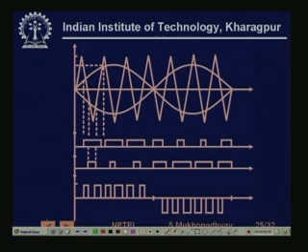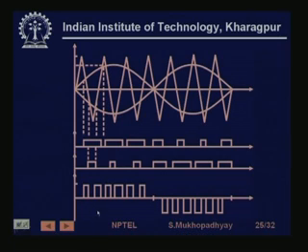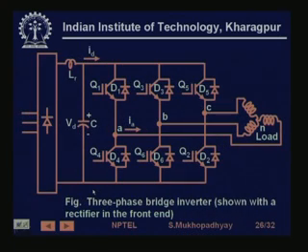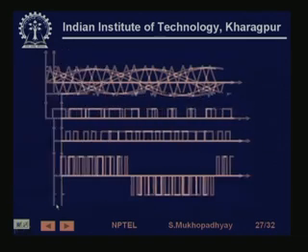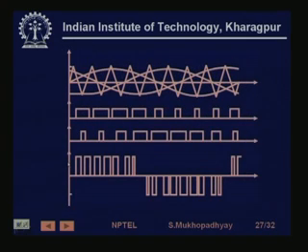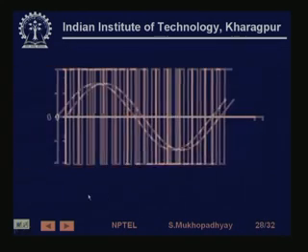So this is what you do. This is again a PWM 3-phase with the motor connected, so there is nothing new in it. If you want to generate 3-phase supply, then you use 3 waves, VA, VB, VC, and then with respect to these 3 waves you actually generate the PWM waves. So that is the way it is done. We are not going into this.